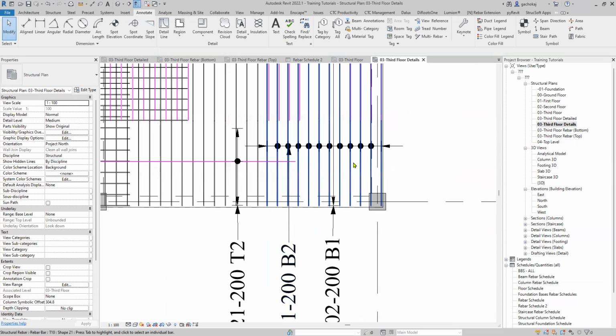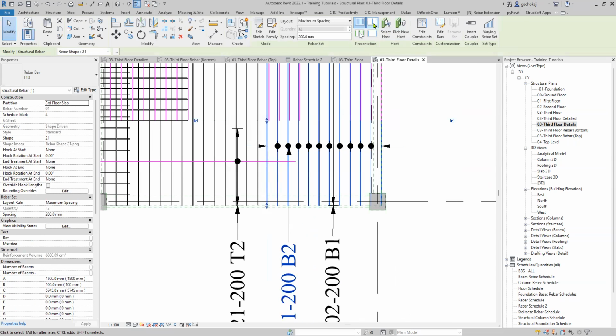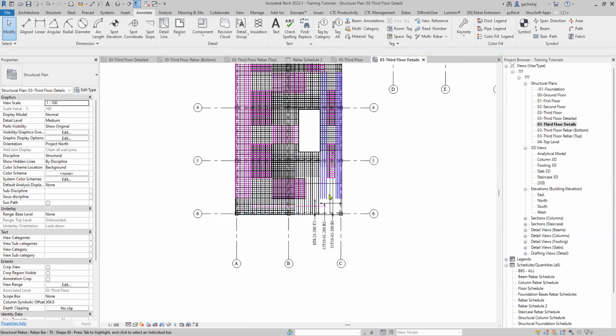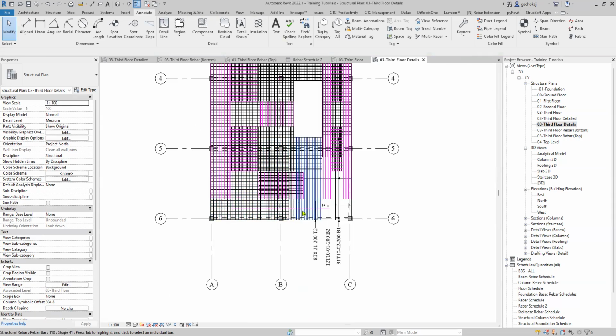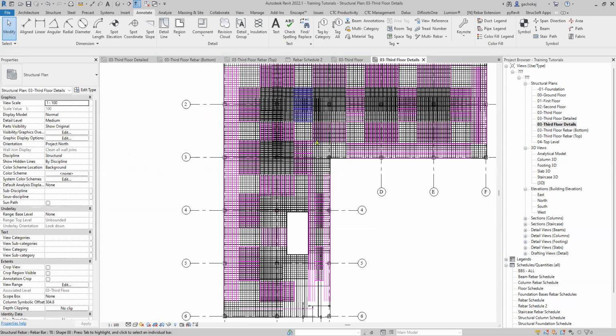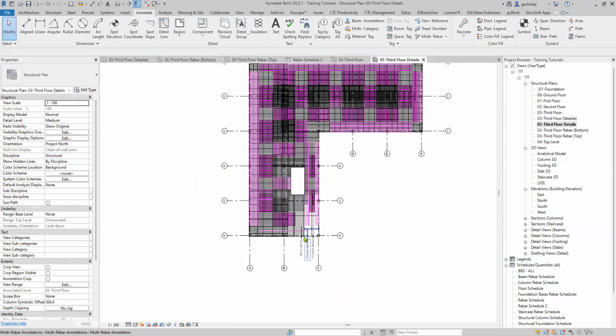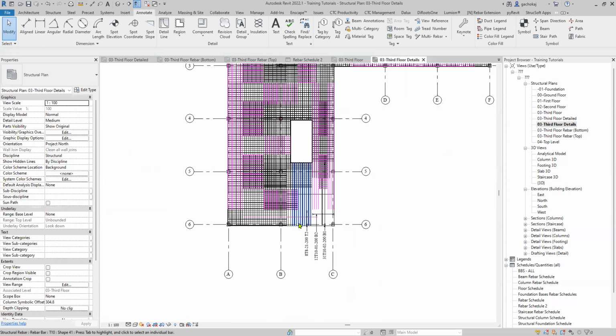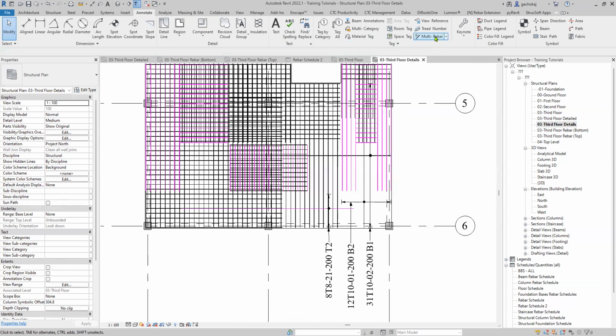You align multi-rebar tag, select the bars, and then simply under presentation, show middle rebar. So as you continue tagging, your bars will continue showing middle and your meshwork will become more organized. So anywhere where the bar doesn't show middle, you'll just know that you still haven't tagged the bar.